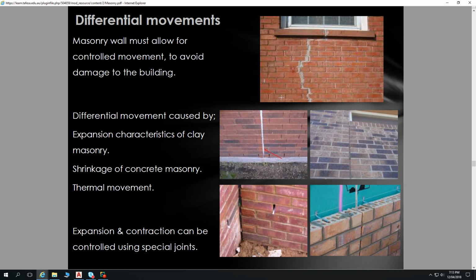And that will typically result in more issues. That sort of thing typically opens up and closes with a bit of seasonal moisture swelling and contraction, swelling and contraction. That vertical cracking is typically something that relates more to, how to say it, not such a seasonal issue. There's something drastic occurring.